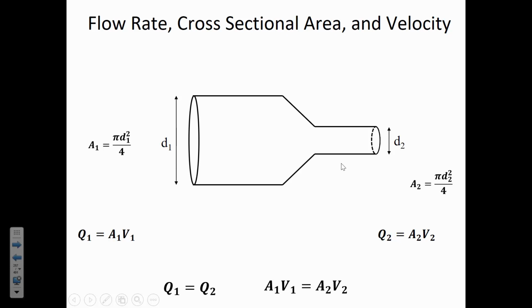And keep in mind the idea of vapor pressure. When we started the semester talking about fluid properties, one of the things we talked about was that each fluid has a tendency to go into the vapor phase. Fluids like alcohol have a higher vapor pressure than water, and what that means is that they evaporate faster and they're much closer to boiling at ambient temperatures. Well, another way to get things to boil besides raising their temperature is to reduce the pressure that surrounds them. And so you'll remember we watched a video of water in a vacuum bell that was boiling, simply because the pressure that surrounded that water decreased.